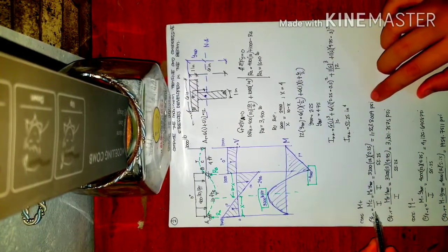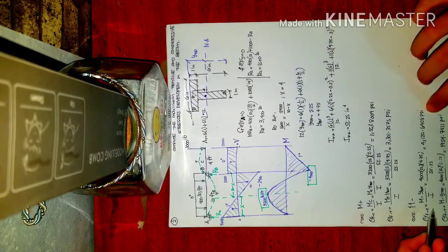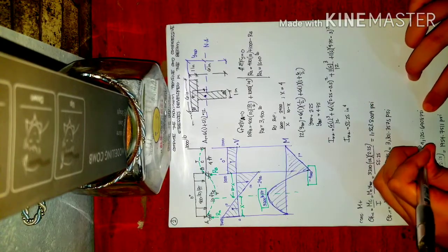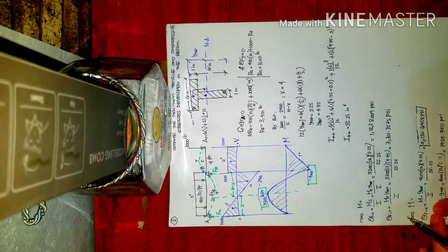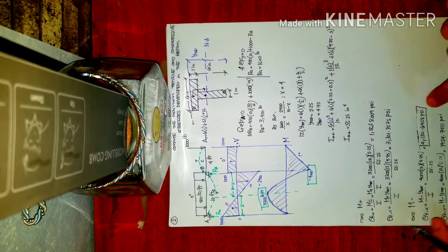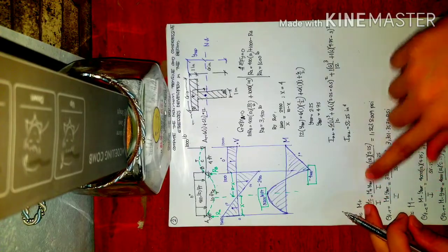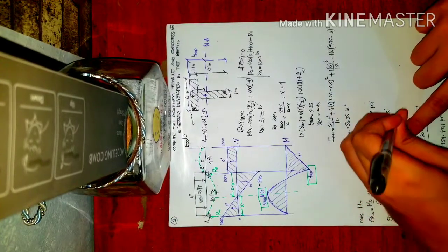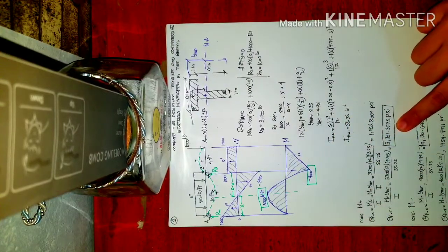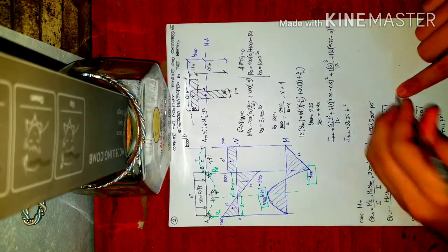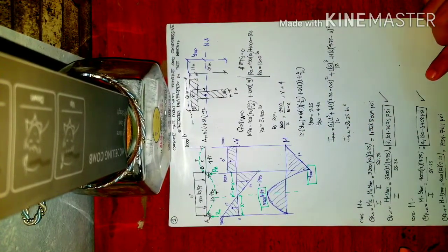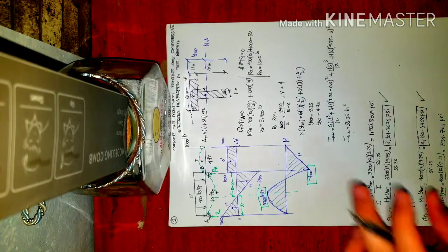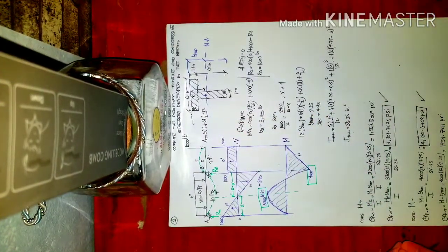So i-compare mo yung compressive. So which of these two is the maximum? So ito. So under sa negative moment, dun lumabas yung maximum compressive na flexural stress. And then for tension, compare mo lang. So for tension, dun sa positive moment lumabas, or 3,301.3575 PSI. So ito yung dalawang to, ang final answer. Okay, so ganun lang yung pagkuha ng iyong flexural stress for compressive and tensile under unsymmetric section. Let's proceed with the next problem.